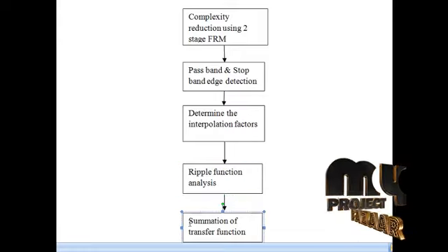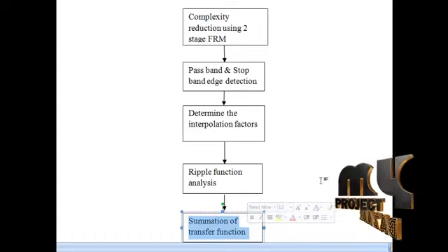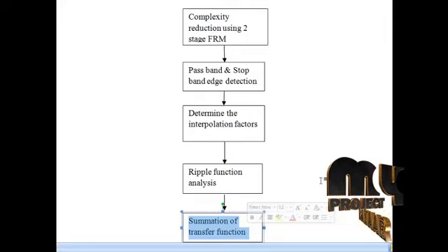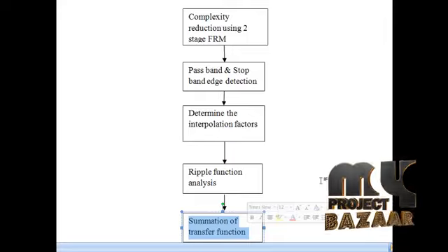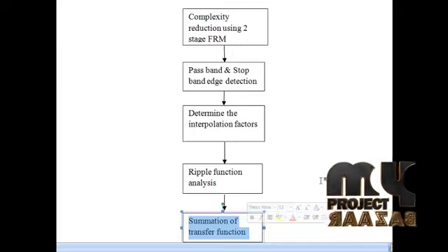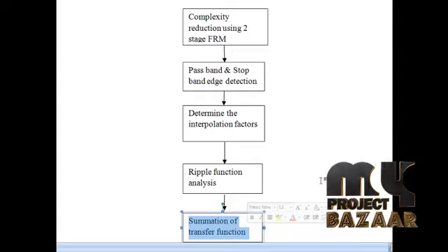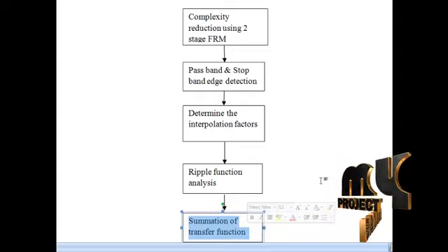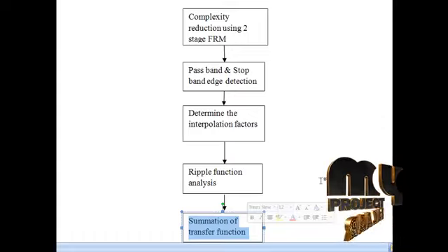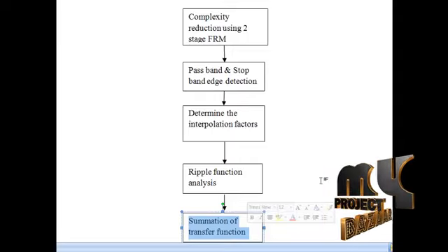The next thing is summing up of all the transfer functions. Initially there are two switches. The input signal is passed through two filters with transfer functions. Then subtract the outputs of the two subfilters and store them in separate latches. That is, the output of one is kept in T1 and the other is kept in T2. The signals in the two latches are passed through a filter with a transfer function. This is added altogether to get the final output signal.